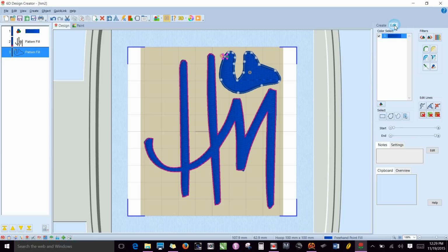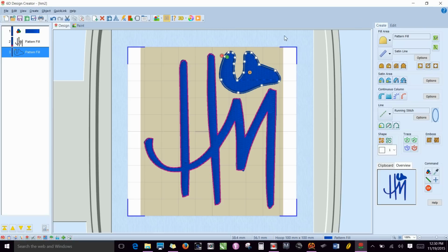And if you need to edit, say you realize that it's not hitting a certain node very well and you want to make sure it hits that particular node, again, go back to the edit tab, edit the lines, and you can hit control to turn a round node into a square node, or you can just click the square node, left click, and it'll turn back into a round node. Okay, so these are kind of silly things, as far as the doodles, but you're getting the point that this is how you use this tool.